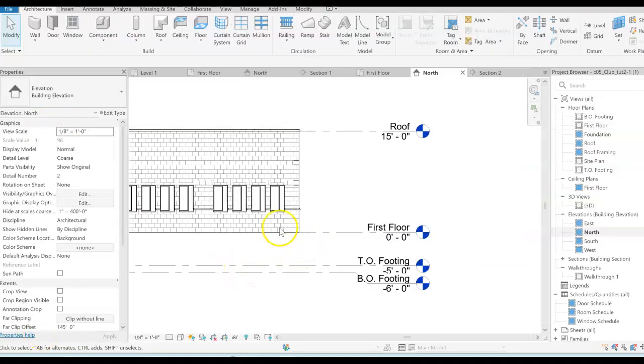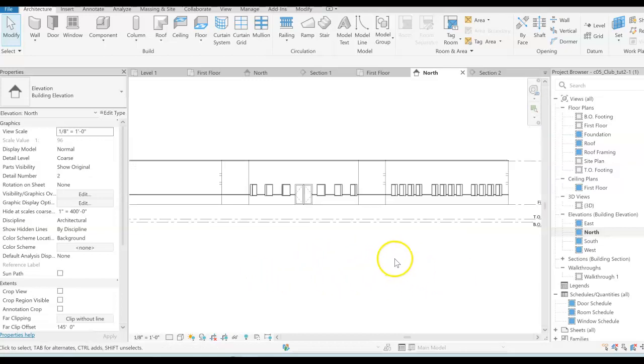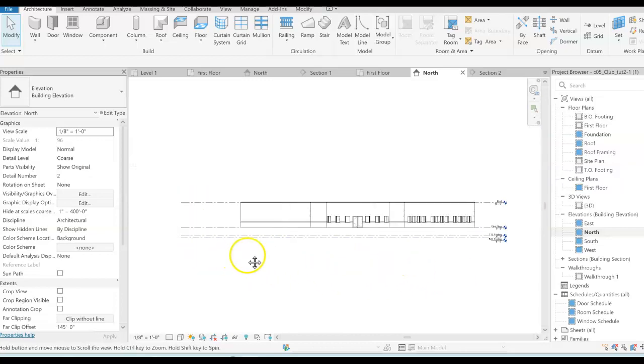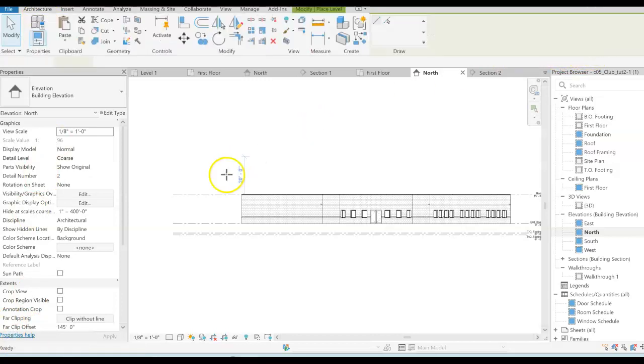Let's do a little off script. Suppose I wanted to add more levels. What if the club wanted to be a 3-story building? I could easily do that. I like to work with the other end, blank end. I will choose my architecture, go to datum, where I found the grid, but right above it is the level.